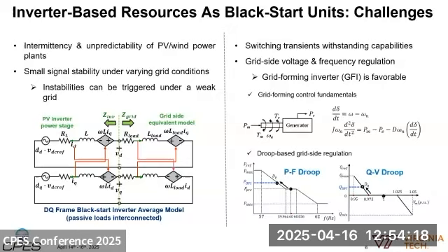And operating the GFI outside of the peak power mode allows the GFI to realize grid side regulation based on PF and QV droop. So the GFI can alleviate the grid frequency and voltage deviation by adjusting the active power and reactive power it injects into the grid.